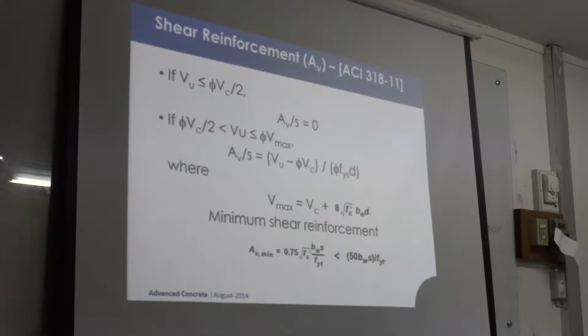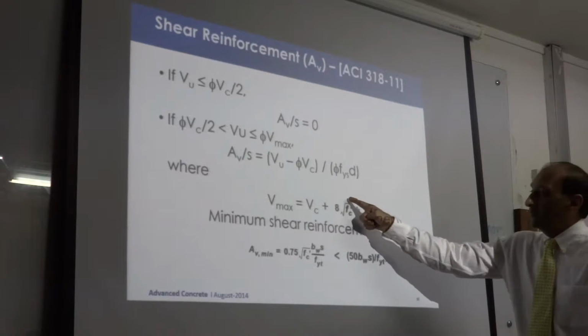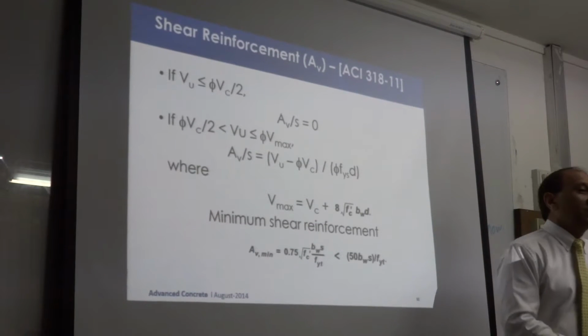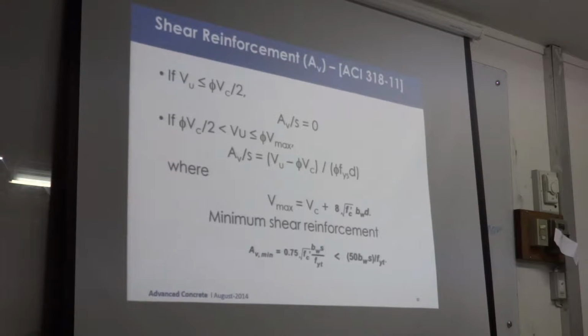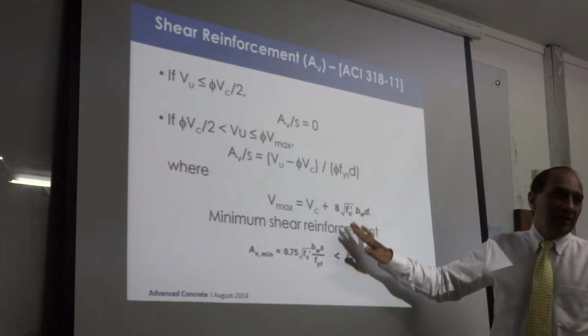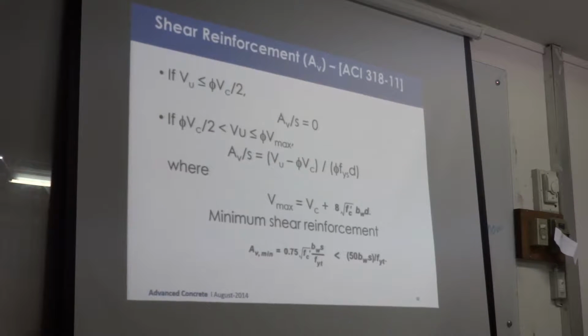So to prevent that kind of shear, which will crush the concrete and lose all other mechanisms of shear, they do not want you to go beyond this limit. And this is a serious problem engineers are facing right now, because when you reach this limit, what do you do? You have to increase the beam width, or you have to increase the beam size, or do something else. And many times that is not possible, especially during earthquake loading, right? For that normally governs shear.